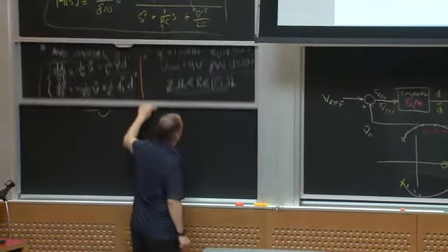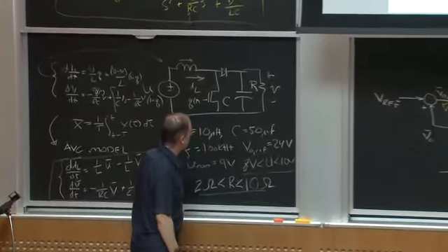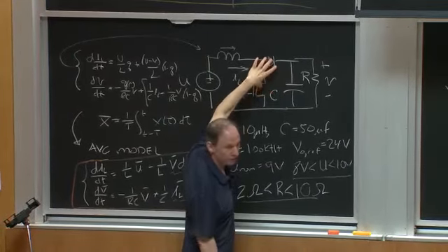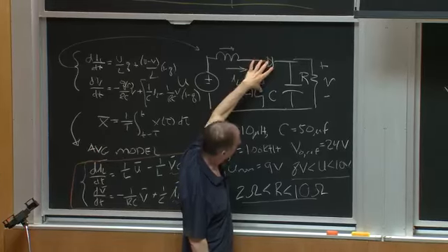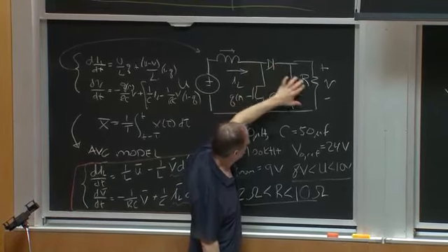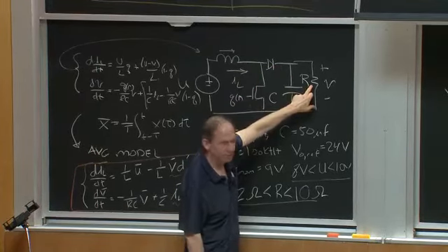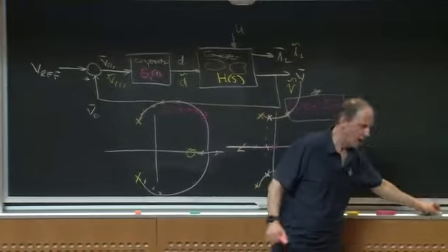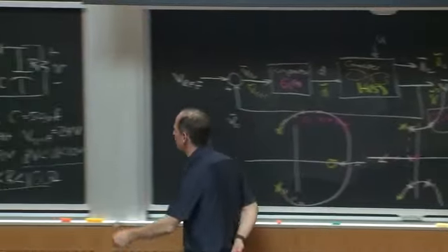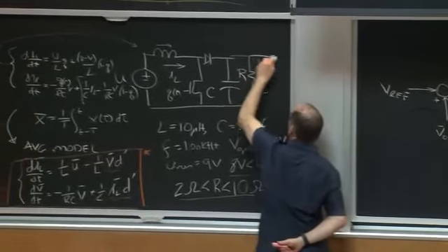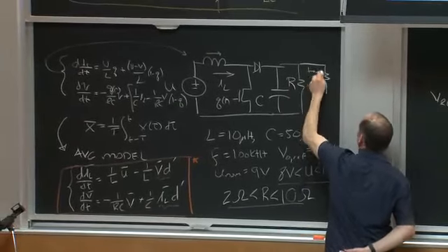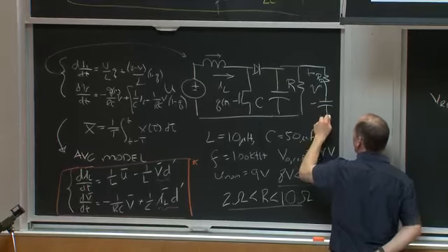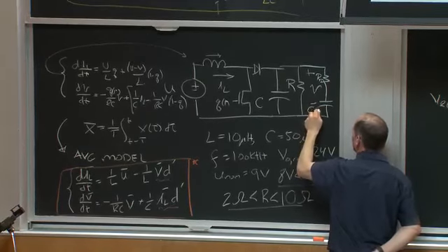And what we saw as one example was that, well, what's really happening is this resistor is damping the LC oscillation modulated through the switching, right? But the problem is when R gets big, it's not well damped. Well, what happens if I walk up to this thing and I say, you know what? I will throw a damping leg on the output of this. I'll put another resistor in here, RD. And here I have C big, right?